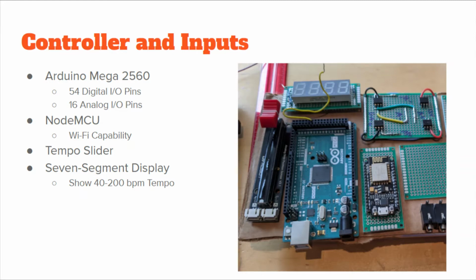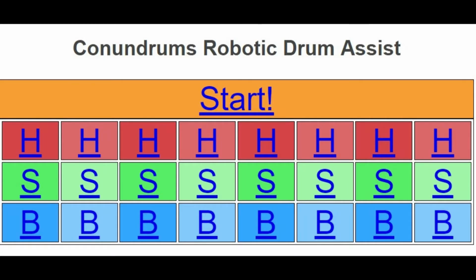2 user input modes were designed for this device: real-time control and beat programming mode. In real-time control, hitting a button strikes its corresponding drum instantly. After holding a button for 2 seconds, the device will automatically strike its respective drum by following the beat at the set tempo. Beat programming mode allows students to select individual half beats and build a repeating rhythm in 4/4 time.